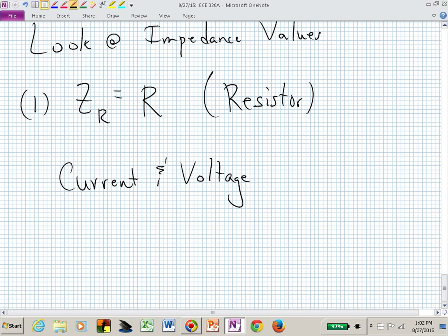They're the same, aren't they? They're in phase. Or, using our terminology from earlier, theta sub v is equal to theta sub i, if they have the same phase. Now those cosines are moving together. There's no time shift between them if you just had a pure resistive load.